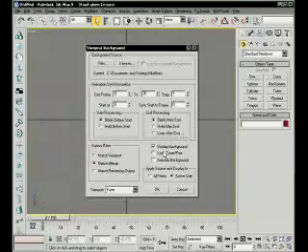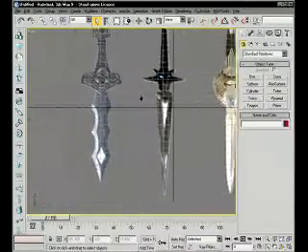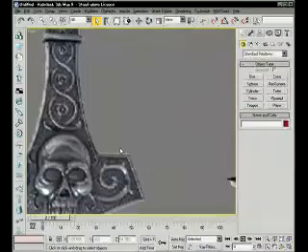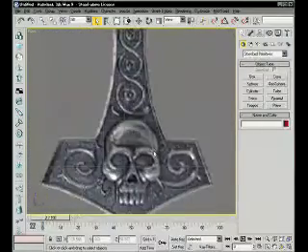This will mean that the bitmap is locked to its scale and not to the viewport, and hold down Lock Pan and Zoom so it won't move around when we are moving the model around. And hit OK. Alright, there we have it. Press G to get rid of the annoying grid, but in some cases it can be useful.